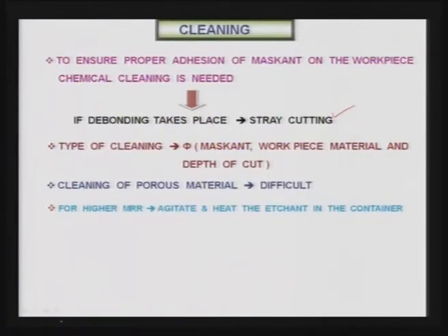For higher material removal rate, as I have shown you in the earlier figure of the setup, agitation will increase the chemical machining rate, and heating of the etchant will also increase the machining rate. However, you have to control the temperature of the etchant, otherwise a lot of loss of etchant will take place and it will make the process uneconomical, and if you are agitating too much or heavily, that also may not be desirable.